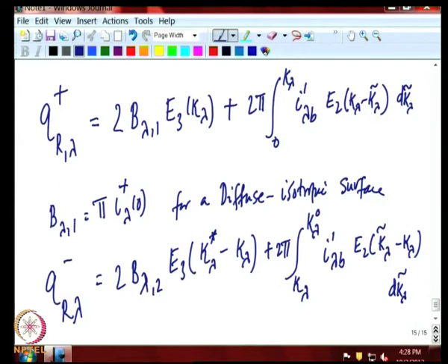So, the second equation right now here is the radiation leaving surface 2 at the top going downwards after attenuation through all angles. The second term is gas radiation emitted downwards integrated over all angles, taking into account the different attenuation of the ray depending on the angle. So, angle plays a very important role here, and so we will now illustrate this.